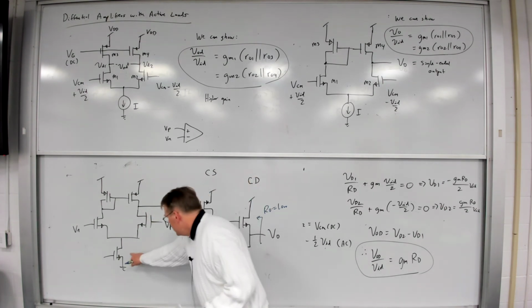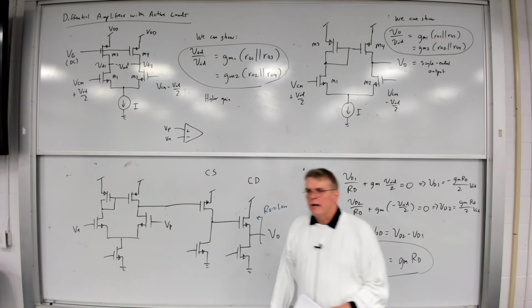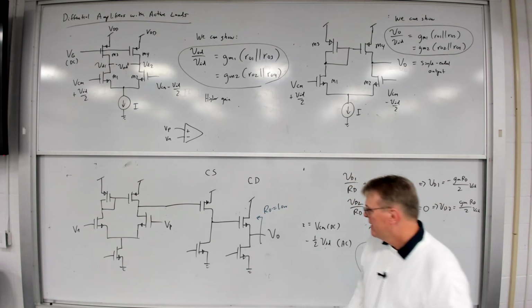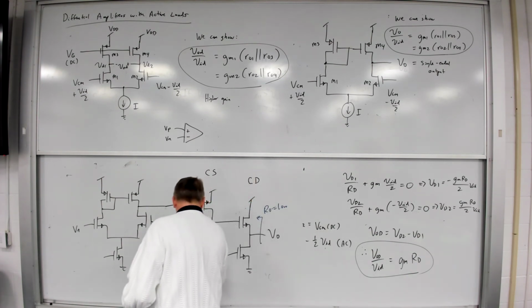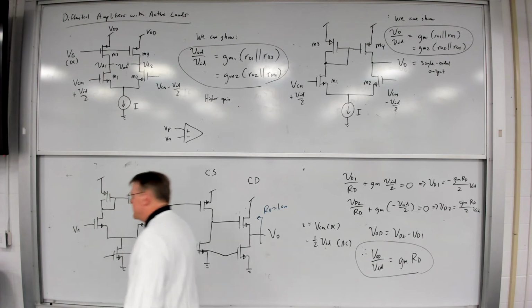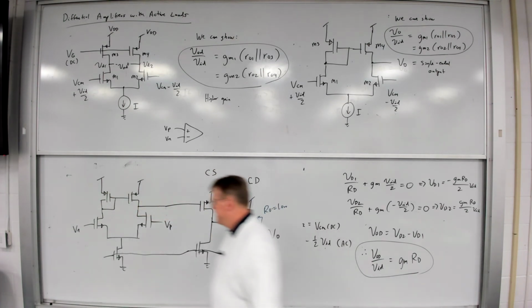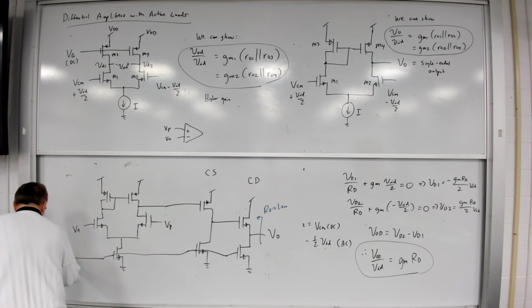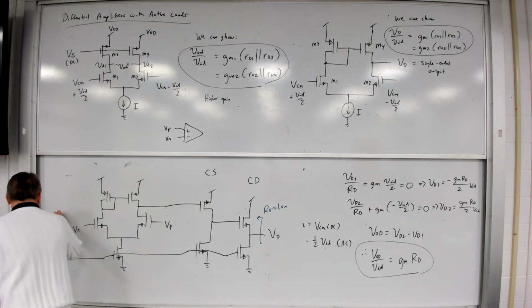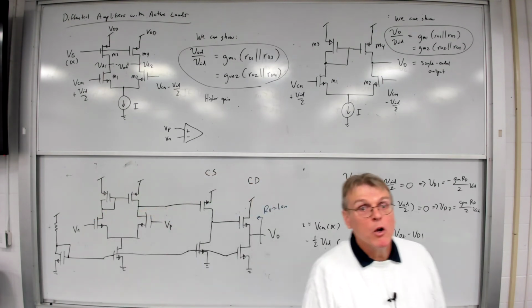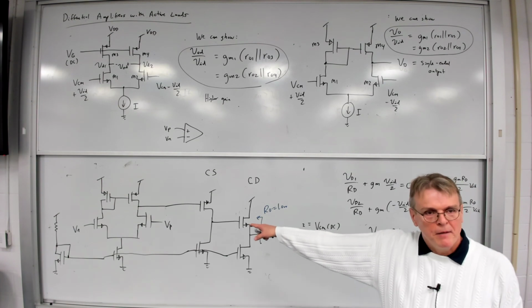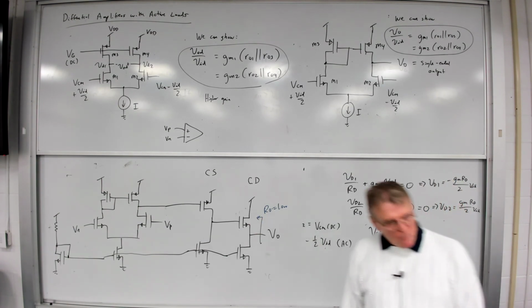Now notice, in each of these cases there is a transistor acting as a current source. Hey, let's take all of these and let's connect all those gates together. And then let's go over here and connect them to a circuit to bias them all together. There's your bias circuit. That is a simple, this is called a Miller op-amp circuit. That is a simple op-amp. Anybody can build that. It works actually pretty well.